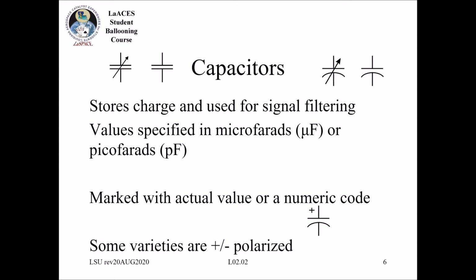Some of these guys are polarized. So that means that the orientation does matter. So I just want to say real quick at the top, whenever you look at this particular schematic symbol, this is a non-polarized capacitor. But whenever I come over here and look at these that have this curve, the semicircle thing, that's usually an indication of it is polarized, but really the true indicator will be when it has this plus.